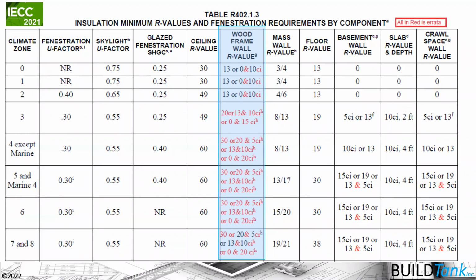So you are given some flexibility here, specifically with your wall R values, but in general, this is considered the most restrictive or least flexible compliance option, because basically the requirement is get that R value in that component of the assembly. So R60 in the attic, for example. You can add more insulation if you want to, but you can't have less than.